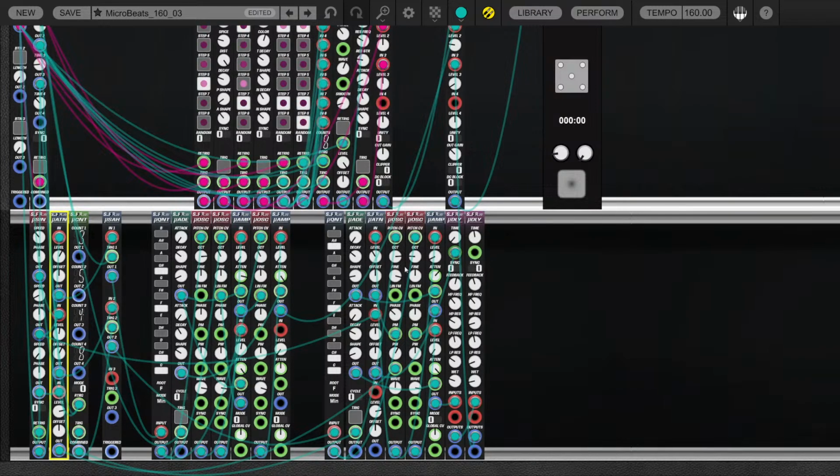We do the same for the accompanying melody line that's also playing here, but we take 2 individual LFO outputs instead of the combined output, and here we have to be extra cautious because these two outputs will output voltages from -5 to +5 volts individually. So in combination we have a signal here from -10 to +10 volts. We need to adjust the attenuator accordingly and turn it down a lot more. And this signal is then also fed into our sample and hold.